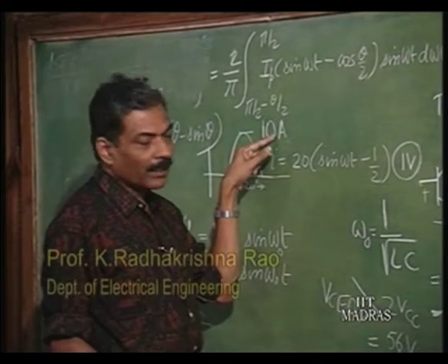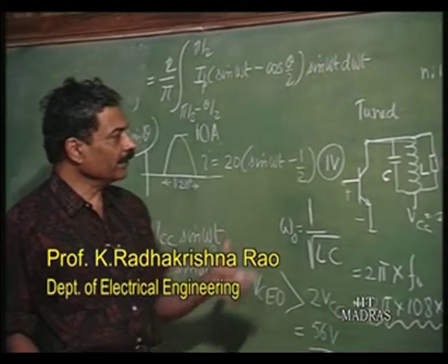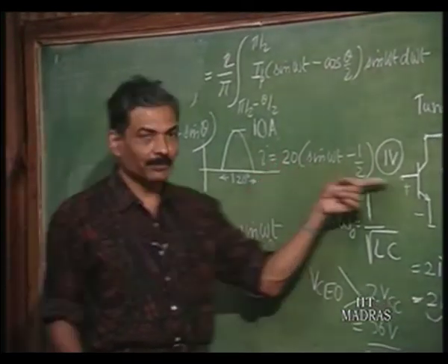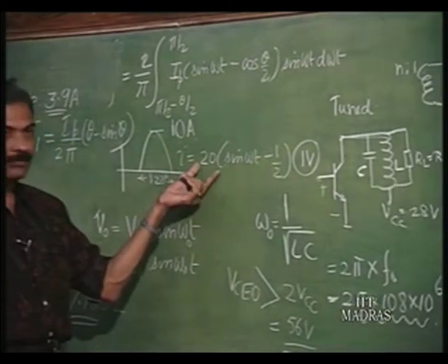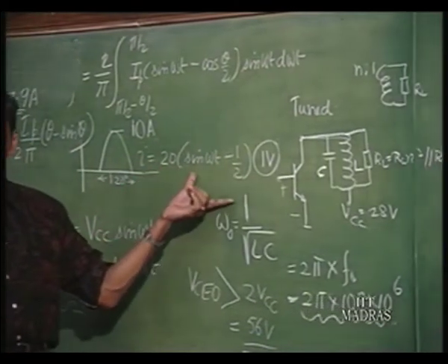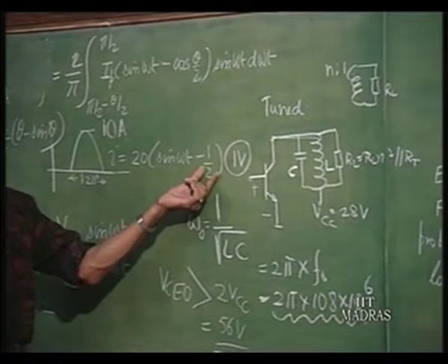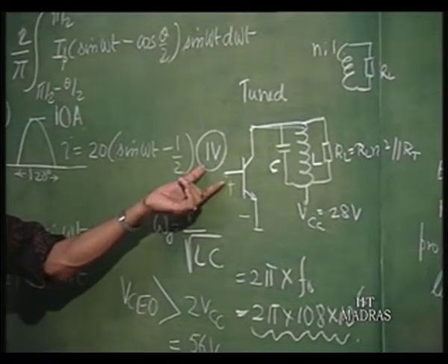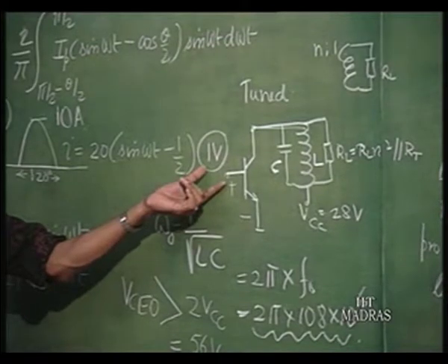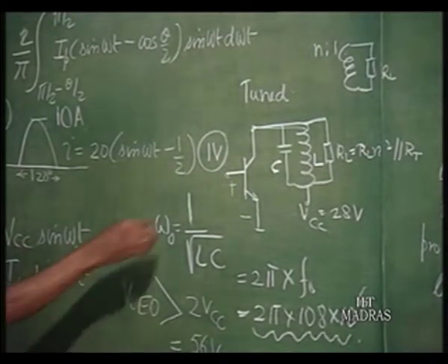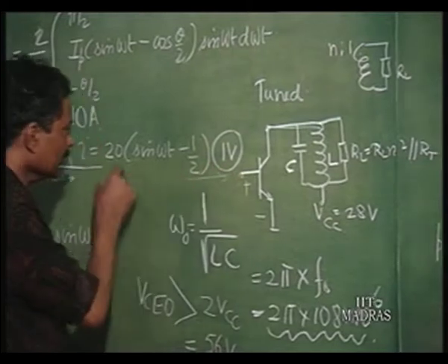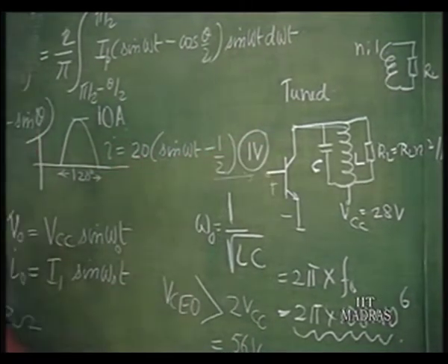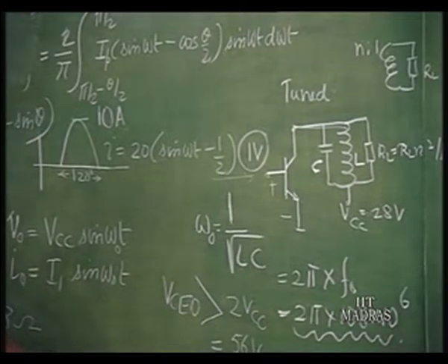And therefore, we would automatically know what kind of current waveform we should have at the input, that is, that divided by beta is what we should have, and it should start conducting for a voltage greater than 1 volt. So, we should therefore input a current waveform like this, which is divided by beta, assuming that beta is known.